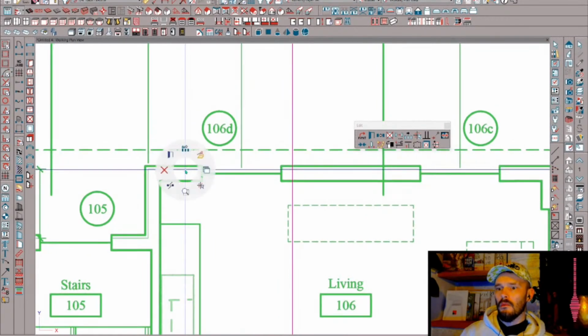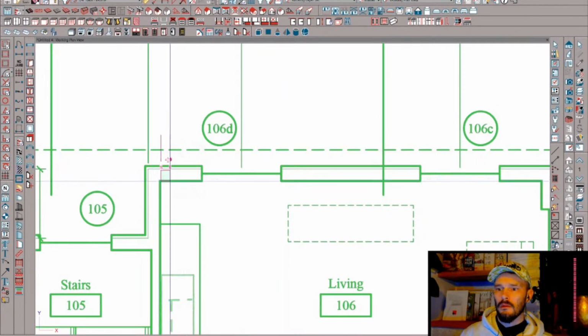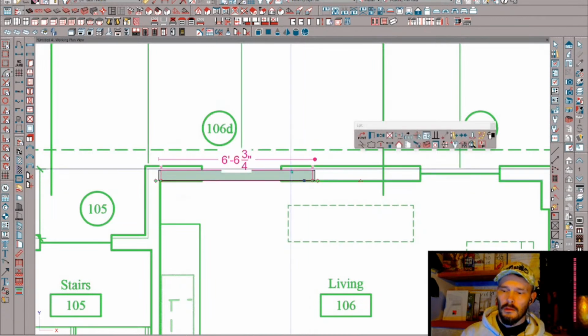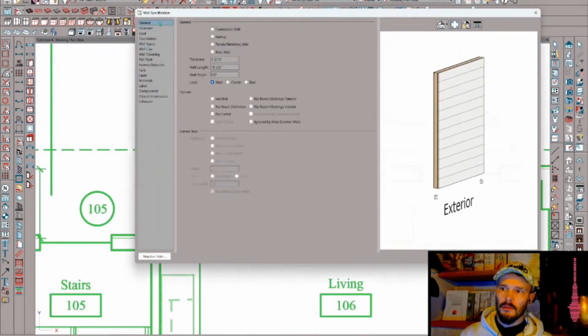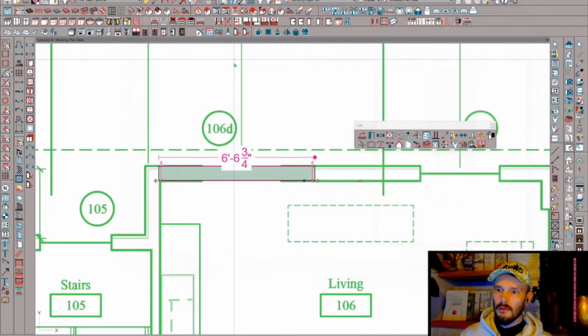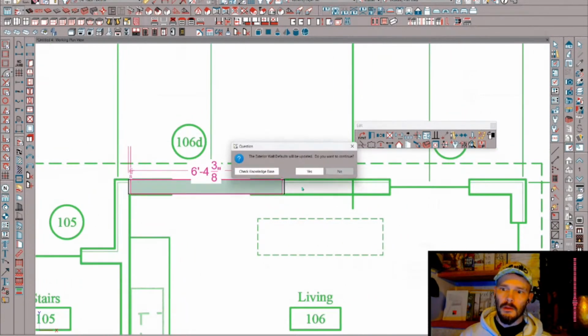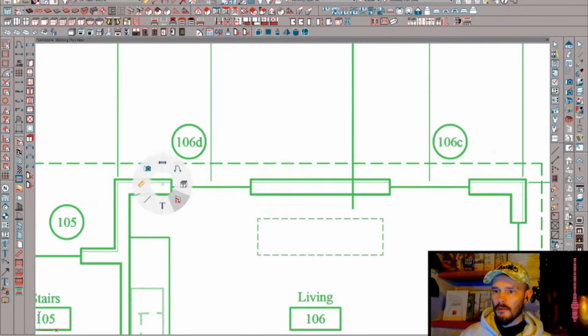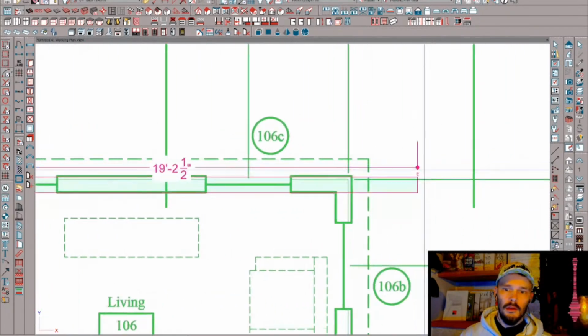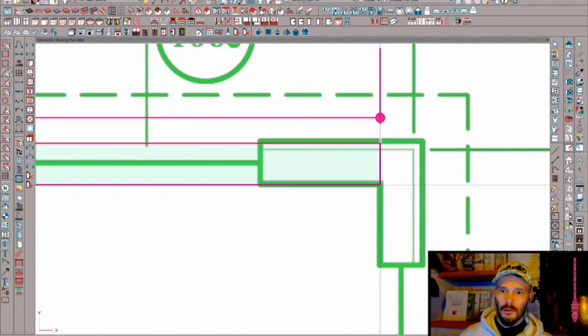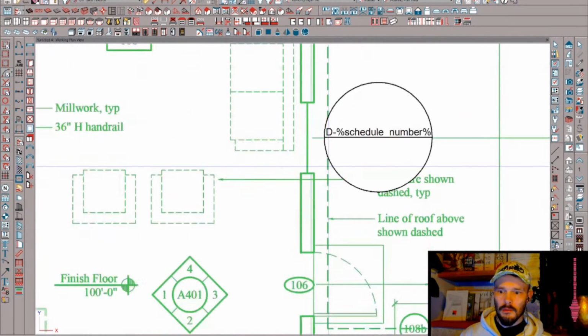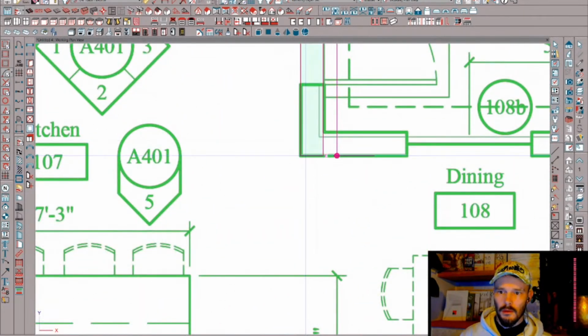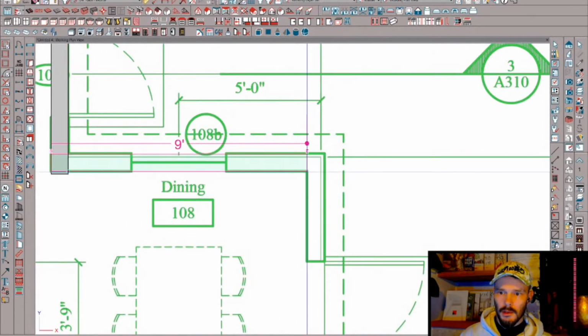So we want to draw a wall out. And let's just pump this up to thickness. Let's go +2. What happens then? There we go. That's it. So default. Yep. And then I just like to start with continuous draw mode. So alternate behavior. So click right in the center of this here. And just continuous draw mode with my 3D mouse makes it real easy to pan and move, and pop this right in place.